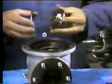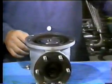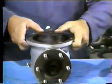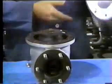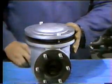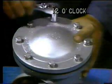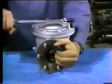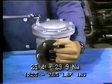Reassemble the valve by inserting the spring, the shims, and the spring seat into the housing. Next, install the piston by pushing it as deeply into the housing as the spring will permit. Install the cover with a new cover gasket. The bolts should be tightened in several steps to keep the cover from tilting under spring and piston pressure. Tighten a bolt at 12 o'clock and another at 6 o'clock. Finally, torque the bolts to 25.4 to 29.9 Newton meters.